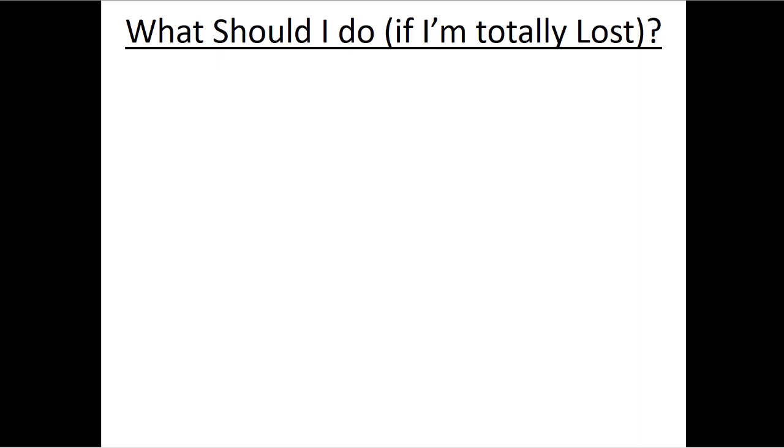So you might get to a point on a test, and I hope this doesn't happen, where you feel totally lost. If you get to that point, what I want you to do is follow these steps. So look at the type of problem that you have, and if you can, draw a PV or a Tv diagram. That might help you understand what table to look at to fix your states.